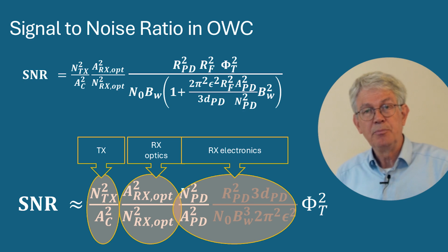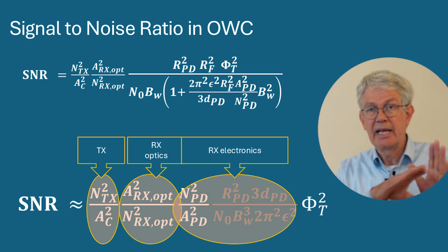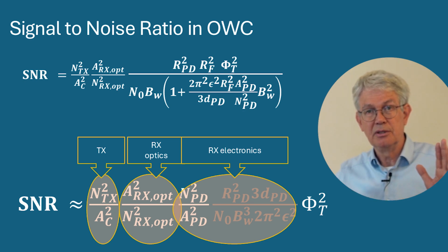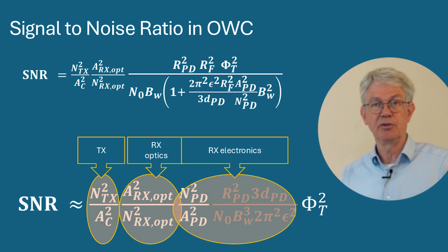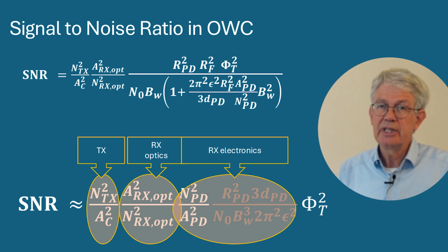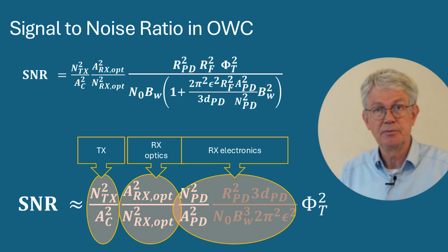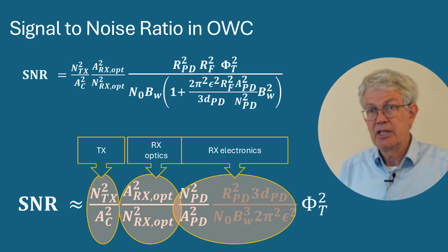A problem with transimpedance amplifiers is that they can equalize the signal response. They can undo the effect of the capacitance of the photodiode. But quite often that comes with an increase of the noise, particularly at high frequencies.